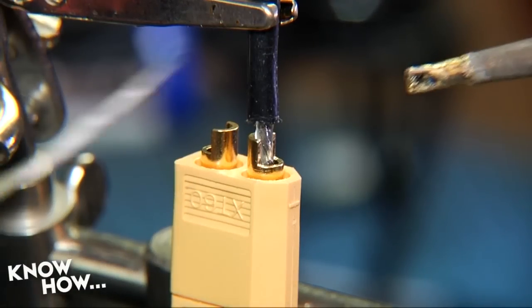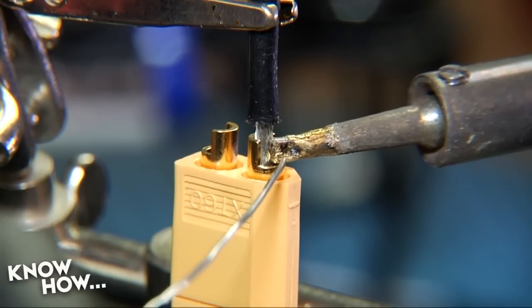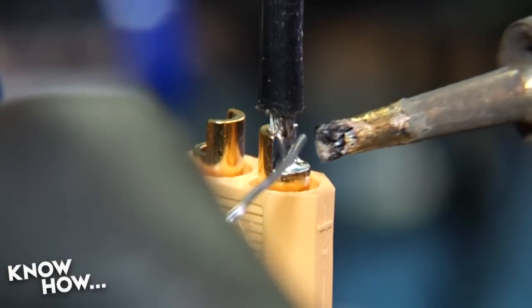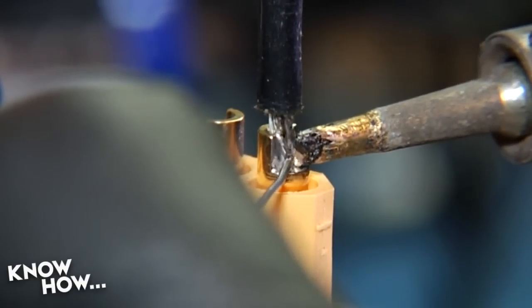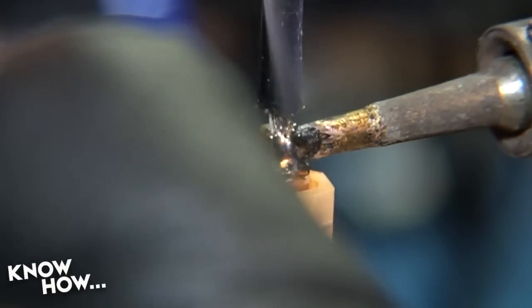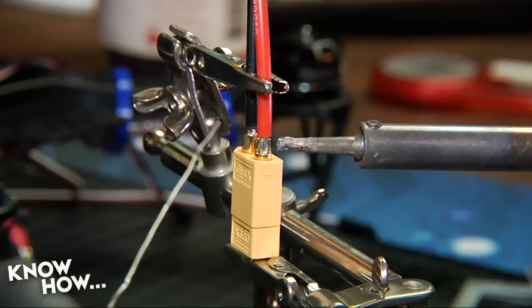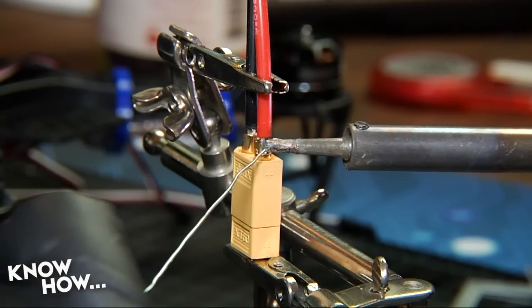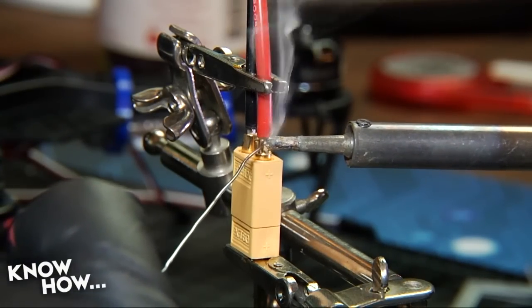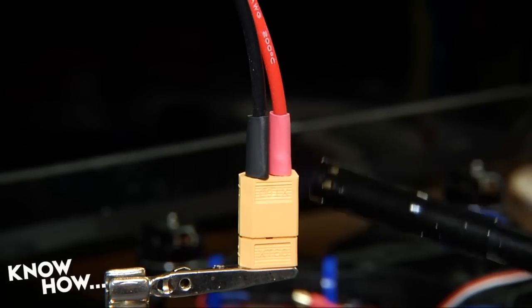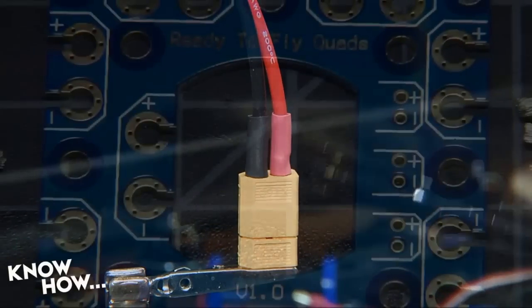Take the black wire and insert the 10mm stripped end into the pin on the side of the connector with cut corners. Apply heat to the wire, not the connector, and when the solder on the pre-tinned wire starts to flow, quickly apply solder to the wire and fill the cup. Never spend more than 8 seconds applying heat, and make sure to let the XT60 cool before soldering the other wire. Once your wires are attached, use 3/16-inch heat shrink tubing to insulate the conductors.